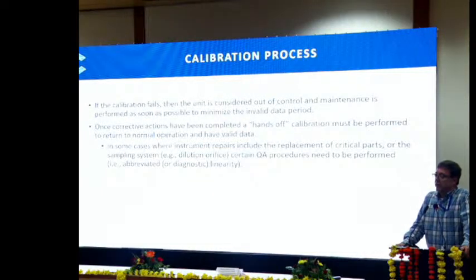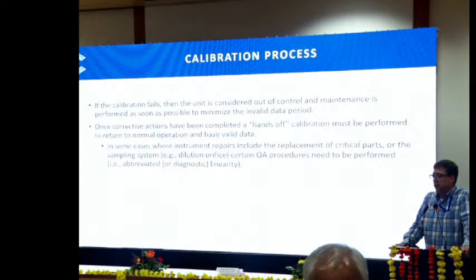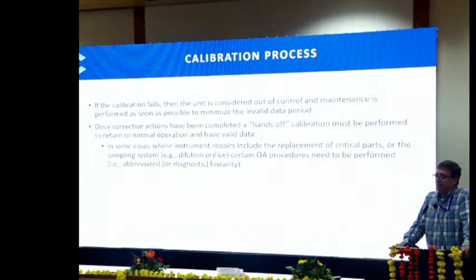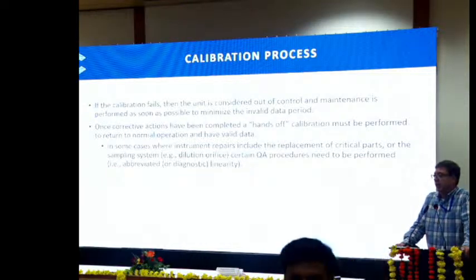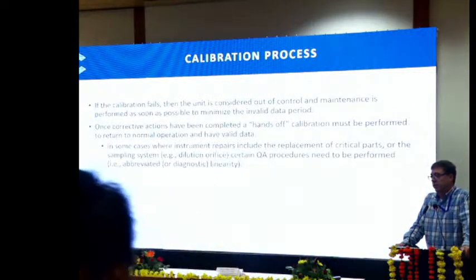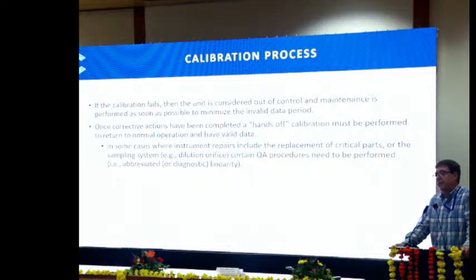If the calibration fails, then the unit is considered out of control and maintenance is performed as soon as possible to minimize the invalid data period. Once corrective actions have been completed, a hands-off calibration must be performed to return to normal operation and have valid data.